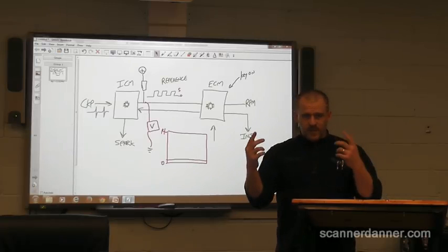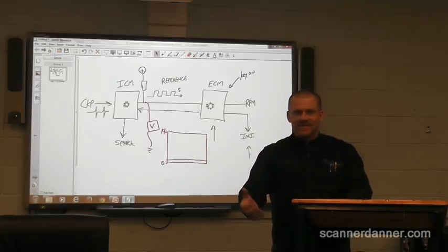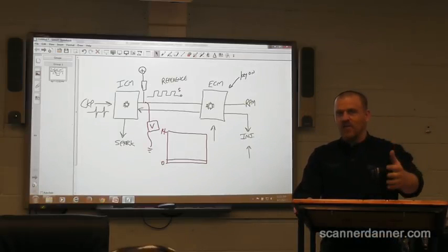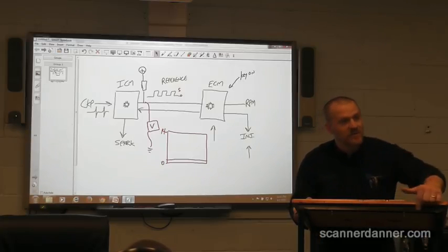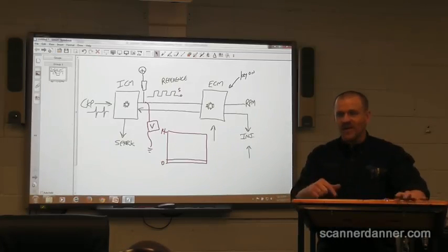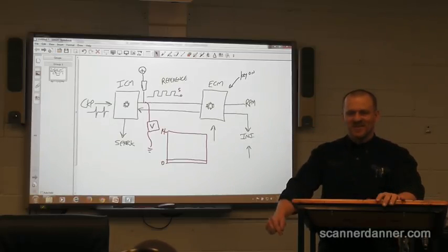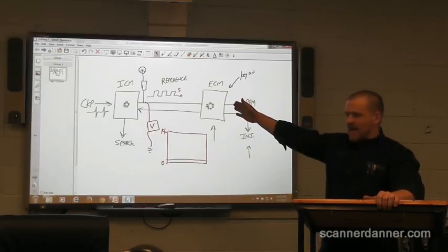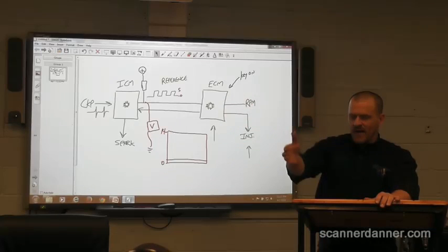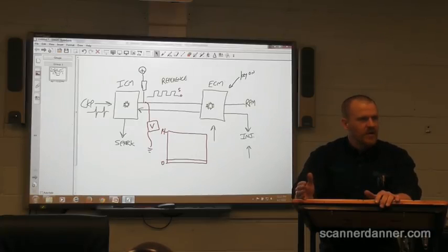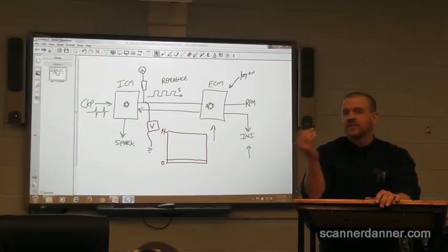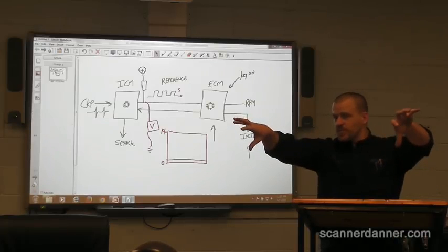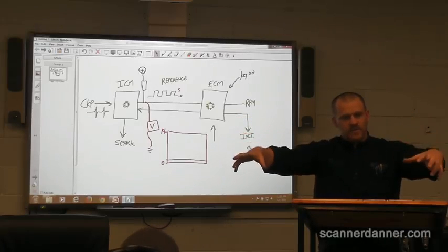Some of this we use some knowledge and theory, and it's hard, I know, in here, and it's easier to see it, but how important is the theory in this application? I know the crank sensor signal needs to be there for spark to take place, so just because I know the theory, I don't need to check the crank sensor. Anyway, this particular test that I've done is I am at a fork in the road, I'm turning left or I'm turning right. If I touch this test light on and off of here and I get a reaction, I'm turning right. If I touch this test light on and off here and I don't get a reaction, I'm turning left. And I have two separate groups of variables within this turn.